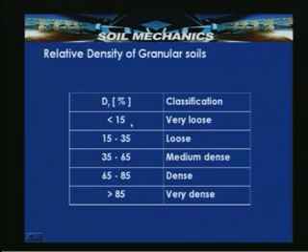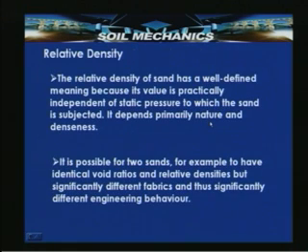Soil with relative density less than 15% indicates very loose packing. The relative density of sand has a well defined meaning because its value is practically independent of static pressure to which the sand is subjected. It depends primarily on the nature and denseness of the arrangement.